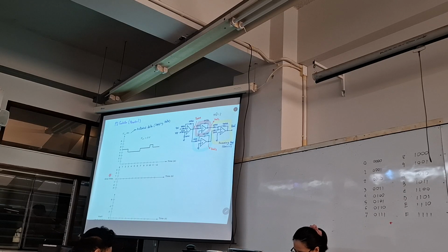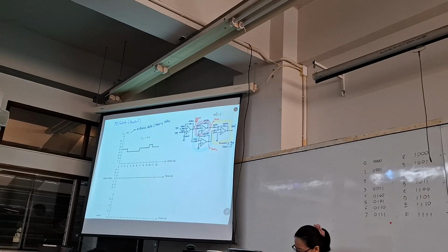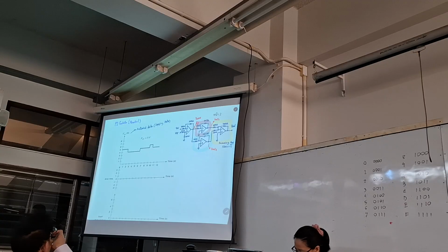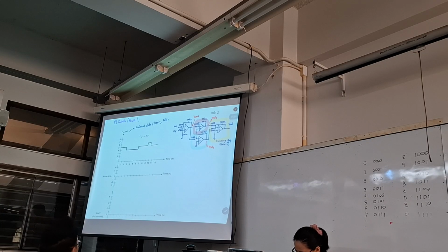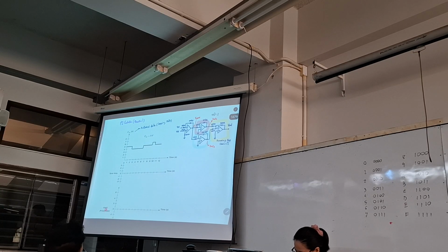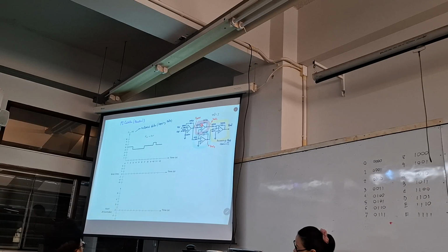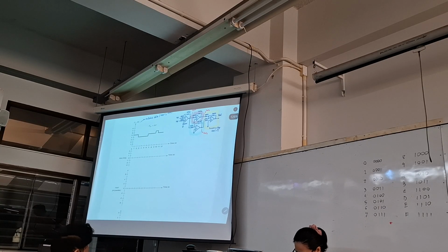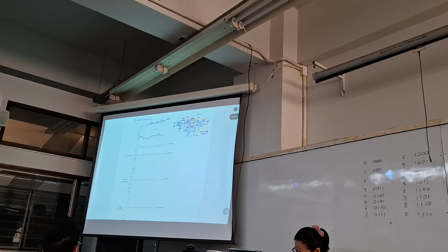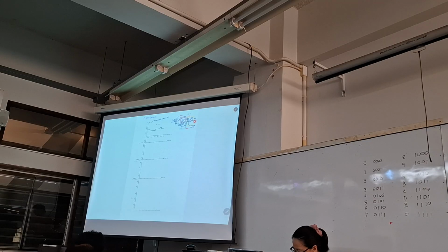What is this error amplifier? Error amplifier is V error in this position, the output from the differential amplifier. Where is Vout1? Vout1 is the output from the P controller. Where is Vout2? Vout2 is the output from the integrator. Where is Vout? Vout here is what you measure at the output of the controller. That is the combined effect of P and I.